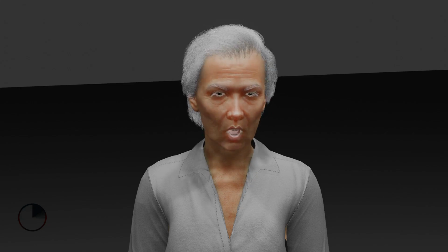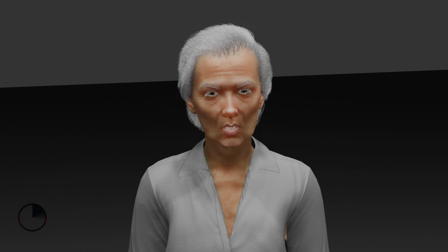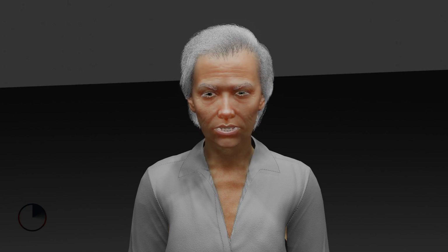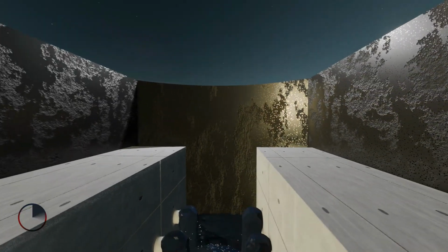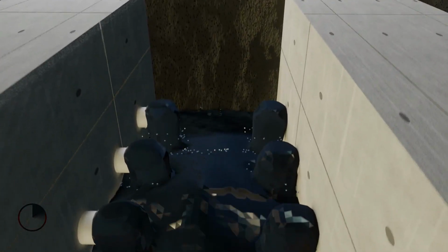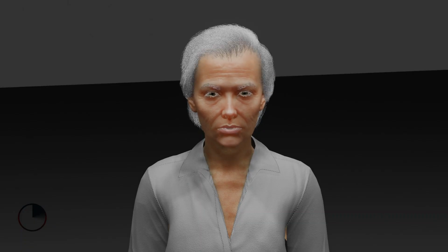This, along with the head drop of the stream or river, are the two values necessary to calculate the available power. Flow rate simply represents the volume of water that can be captured and then redirected by a dam to flow across a turbine generator in order to move it and generate electricity.